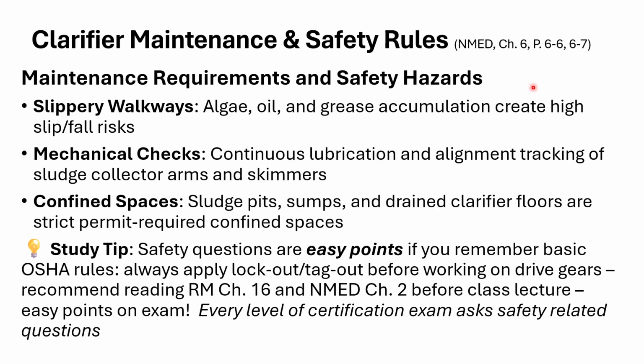Okay. So, with respect to clarifiers, we have these catwalks we've been seeing on the primary and secondary clarifiers, right? Well, any algae buildup there, any oil or grease that accumulates there, you can have the whole slip, trip, fall hazard there. So you want to keep those free of not just debris, but of any of these materials that could cause it to be rather slick as a walking surface.